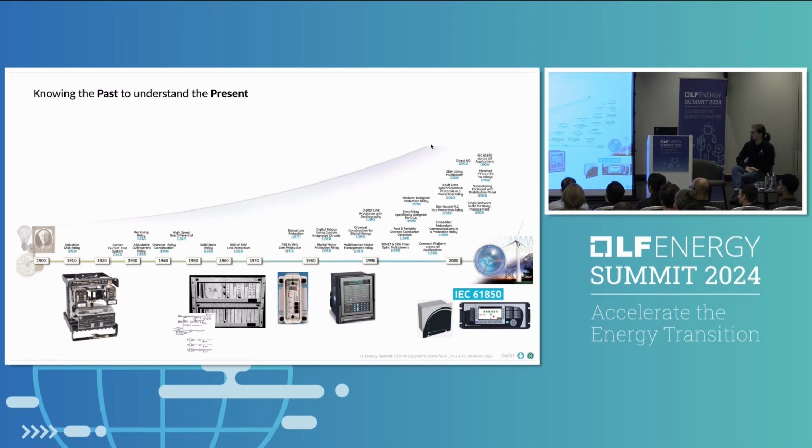So in GE, we invented the electromechanical relay at the beginning of the 20th century. Everything here was mechanical, copper. When the current flows through the copper, it creates a magnetic field. The magnetic field makes one disk rotate, and that disk reaches one contact, and when that contact was reached, the real breaker was opened.